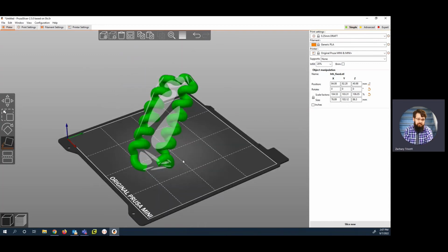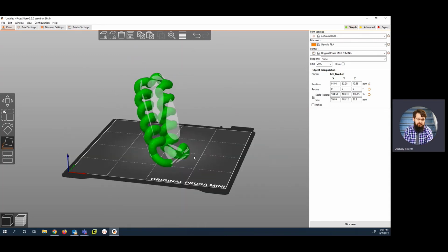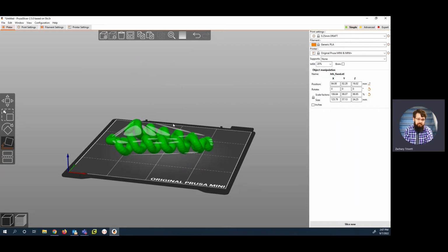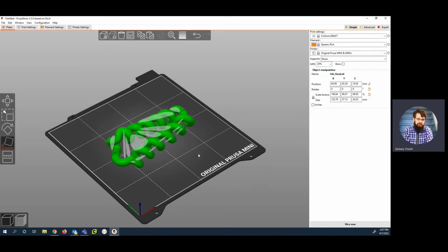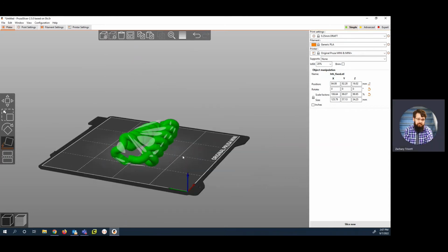So I can even print it up by letting this be the bottom, and it will print in this configuration. Note that there are better configurations for prints. Having as much of it on the build plate as possible is usually the best situation. There are other situations where it's better to print in a different way. Be sure to talk with the Digital Learning Lab to determine that.